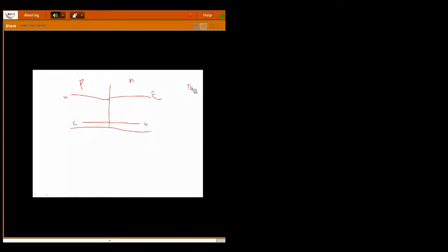Now what is in forward bias? In the forward bias condition, these majority charge carriers, these holes, will enter into the N region due to the diffusion process, and they will become minority charge carriers. These are holes, entering into the N region. I am calling this pn: the first letter p is your hole, and in which material is it? N type. That is pn, which is nothing but minority charge carriers in the N-type material.